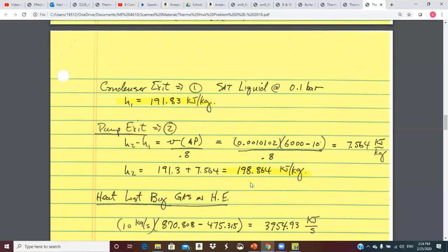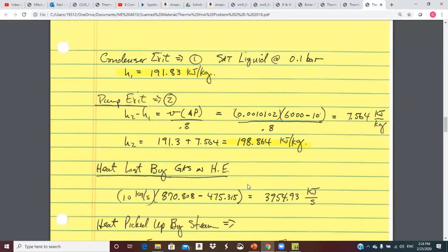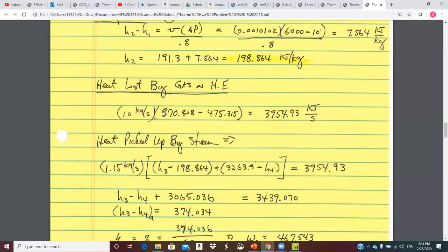Okay? Everybody good? All right. Heat loss. Okay, so this is on the gas side. This is the mass flow rate of the gas. This is the enthalpy difference. So this is the amount of energy that hot gas stream out of the gas turbine is dumping into that heat exchanger that is absorbed by the 2 steam flows. Okay?